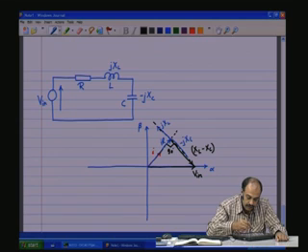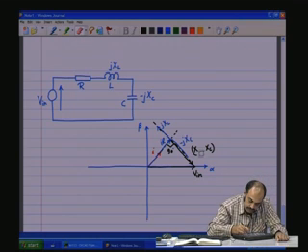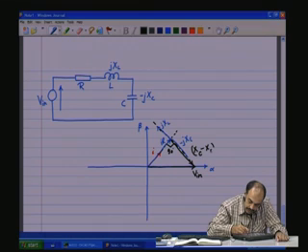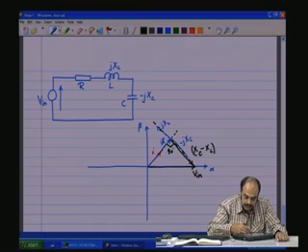Of course, in this case, when we say XC dominates, meaning XC value is more, then we take it as XC minus XL. So, in such a case, the XC value is dominating, and this will cancel out XL, and then that completes the vectorial sum for V. If the current were lagging, which means inductance dominates, the current would be here, and then XL would dominate XC, and it would be XL minus XC.